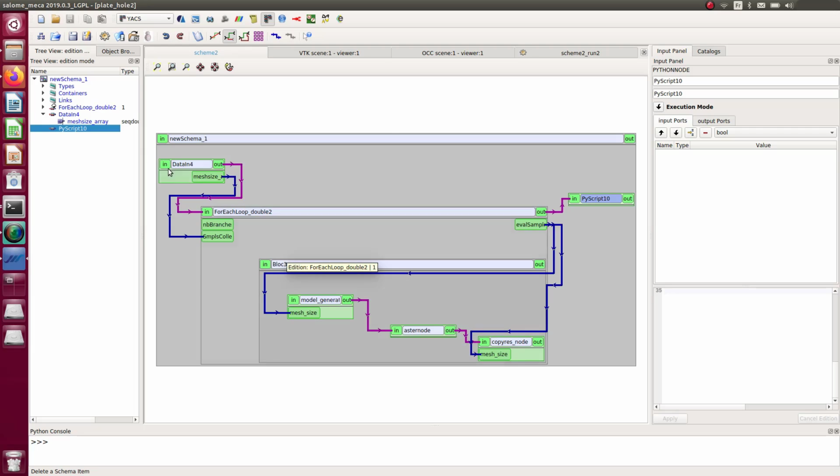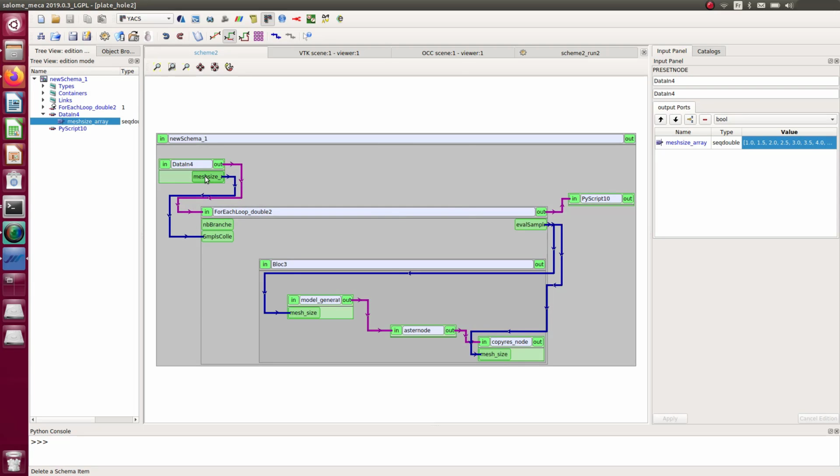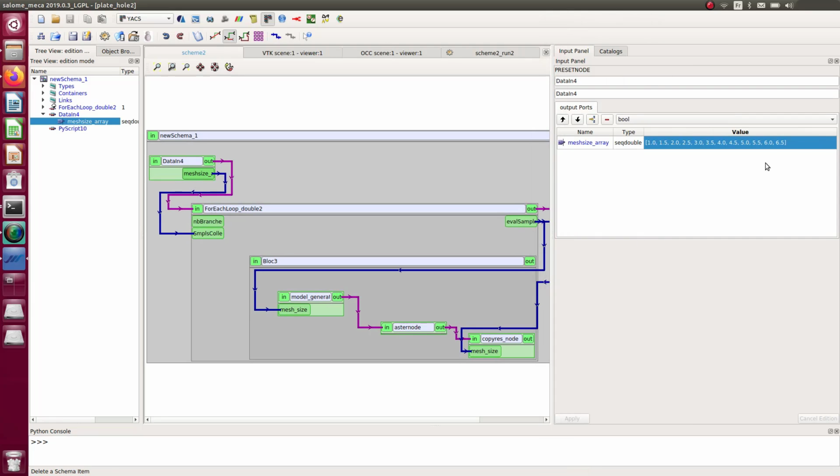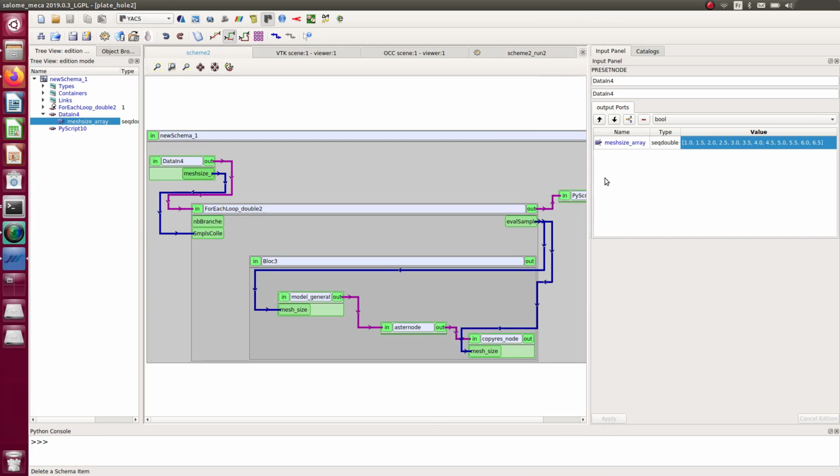It's not a big hassle to have a separate Python script and run it after you run all that in YACS. It doesn't have to be everything in YACS. Now, if you want to get more data points, you need to modify the array here and run the script again. It will generate all the results, and you run the Python script again to generate the picture, and you get your small automation.